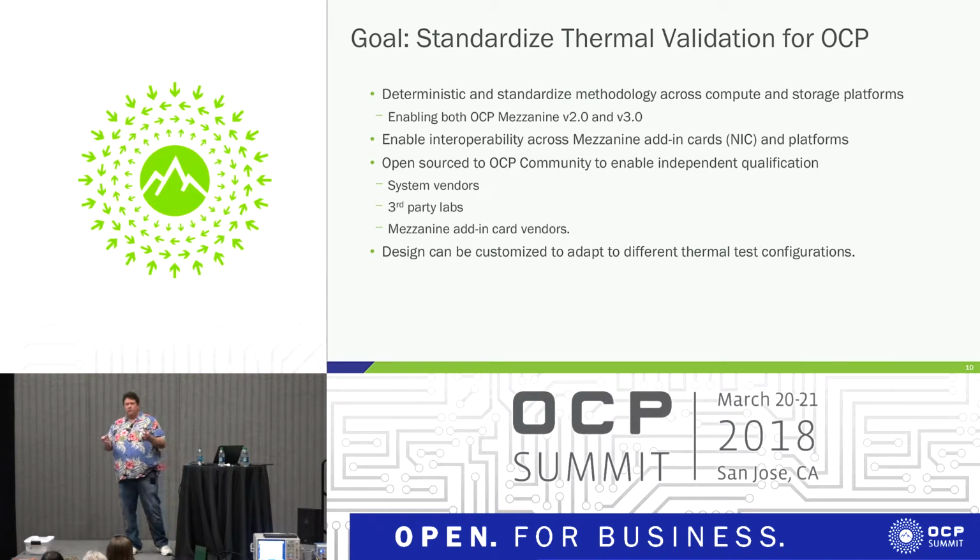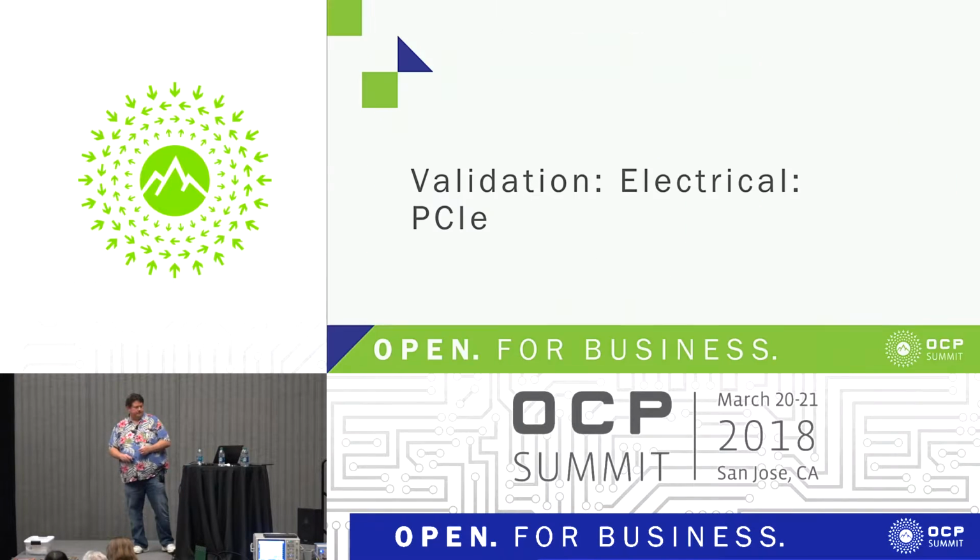But now when the card vendors test their cards, they can all test using the same test fixture, so that if vendor A's data and vendor B's data say the same thing, you know how to adjust for it in the system, instead of saying vendor A used this type of test fixture and vendor B used that type, and they really don't correlate at all. So a common methodology, and you're going to see that in Sumit's presentation as well from the PCIe validation. So we're trying to drive that to where everything is standardized.